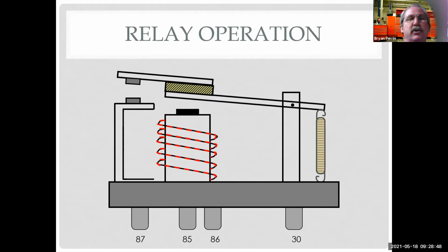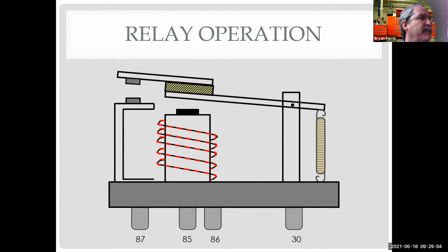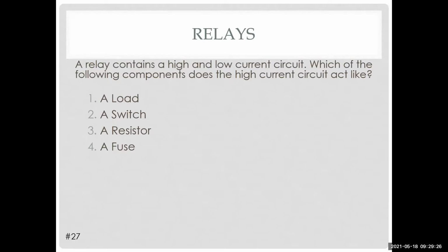But yeah, it is neat how you can control two different sides of the relay with two different switches, and they both need to be on for it to work. So it just allows you to do a lot of cool things. Or another example might be, I only have power going to 86 with the key on or with the engine running. So now as soon as I turn the engine off, it turns the relay off. And I control the ground for when I want it on or off. So we can do a lot of different ways of doing this. So it's kind of built-in redundancy.